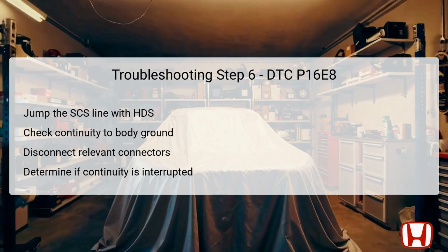If continuity ceases at the disconnection of a specific connector, it indicates that the LIN wire is in good condition, and investigation should shift to replacing the component that caused the disconnection. If continuity persists, this suggests a short within the LIN circuit that requires repair.